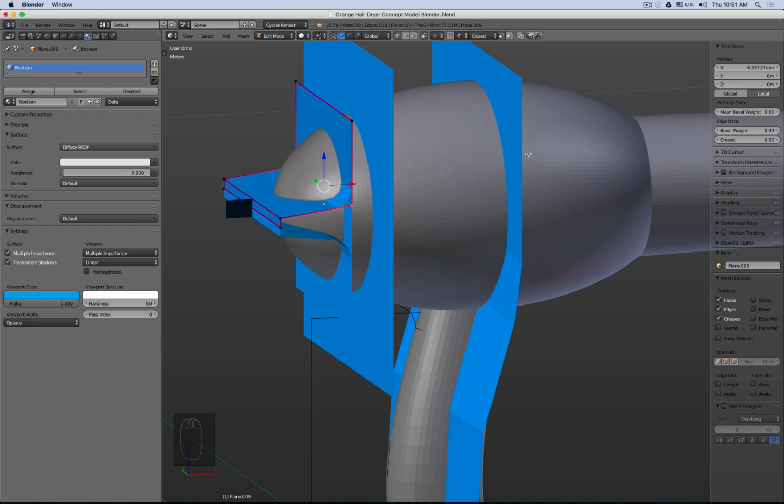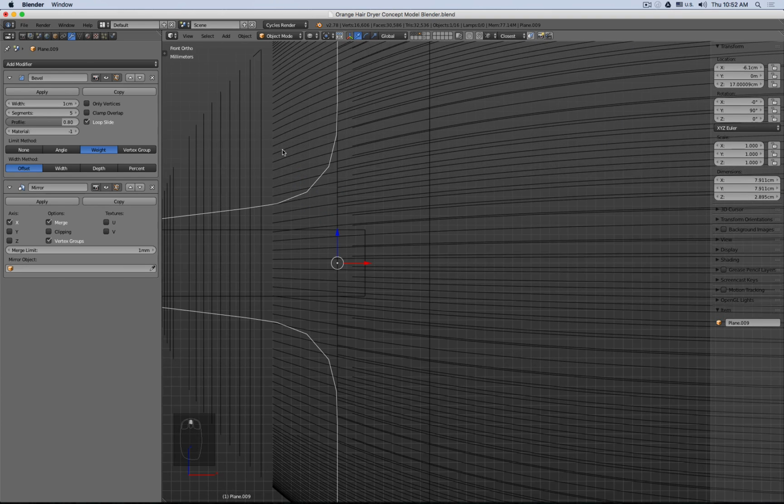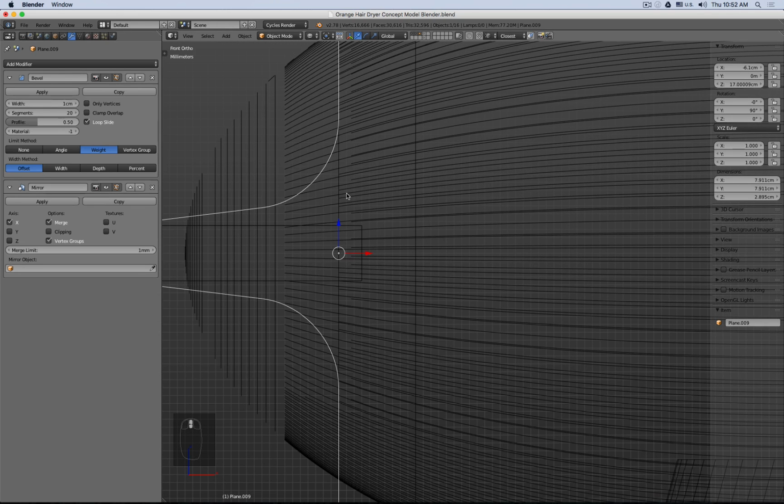The way how this one works is I have this edge fully creased. The other edges are not bevel weight, and I then edge creased the outside edges. And you see that I am using a bevel command. So I have a little bit of nice creative ability to sculpt, for example, the transition. This would be the default. So the fillet G1 or in Fusion, it would do it a little bit better, but I rather want to have more control over it.